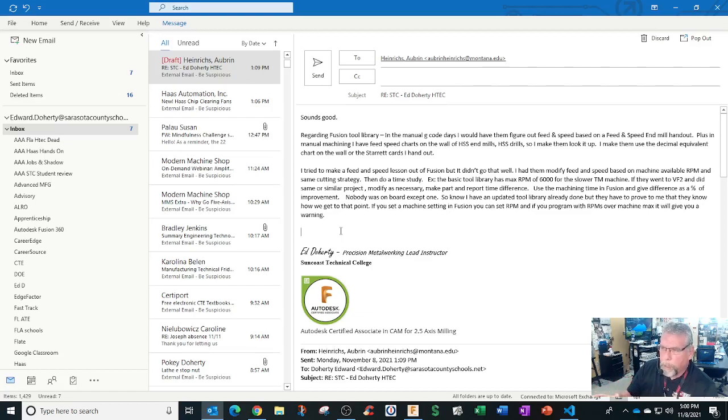I tend to use the probing program a lot. When we do manual G code, that's when I go back and use Edge Finder and manual touch off. So I'm teaching in reverse later on, like you're saying. We're going CAM and probe. We're pumping out parts with the tool library that's already set up, which really needs not much.